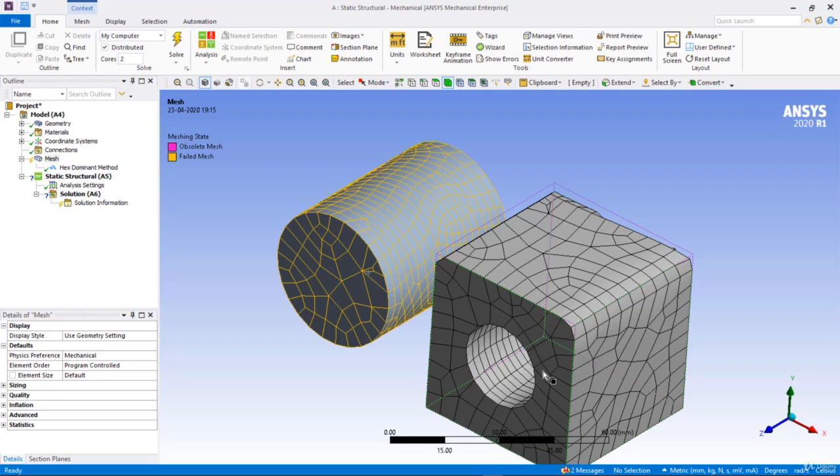We carry out a basic analysis and try to find critical areas and other things, and once we are done with all the basic steps, then if we are going for the final steps, we will see whether we can get a hexahedral mesh or not. And remember, it's a very tedious task, and it's a manual task. No automatic mesher in any of the available software at the current stage can efficiently do that. It can generate some arbitrary mesh containing a combination of tetrahedrons as well as hexahedrons, but not even 50% of this hexahedral mesh is good.